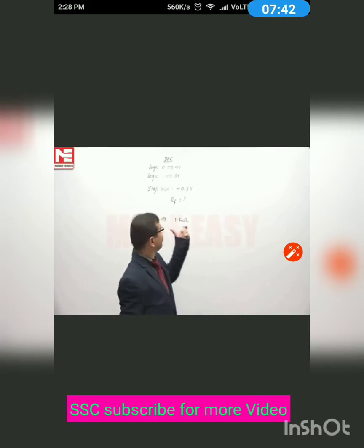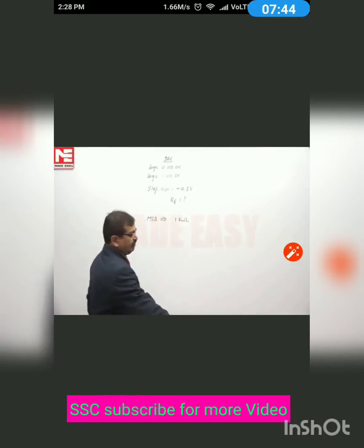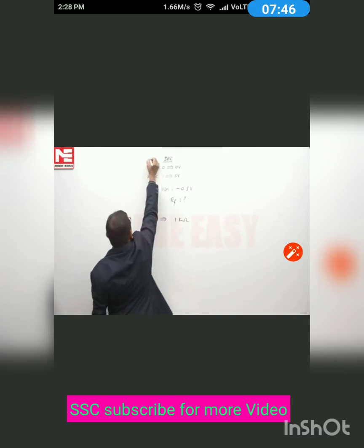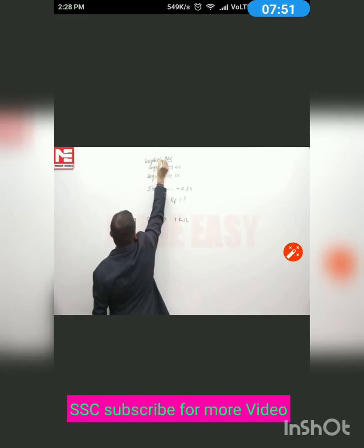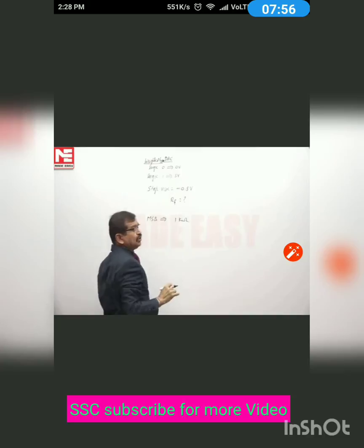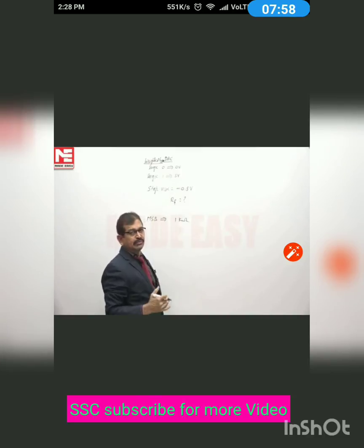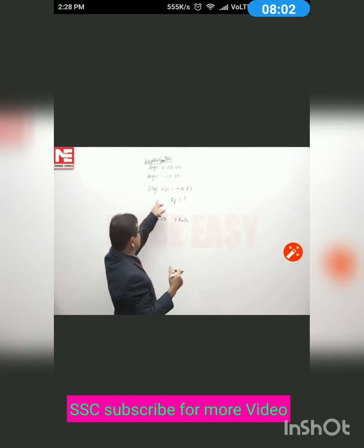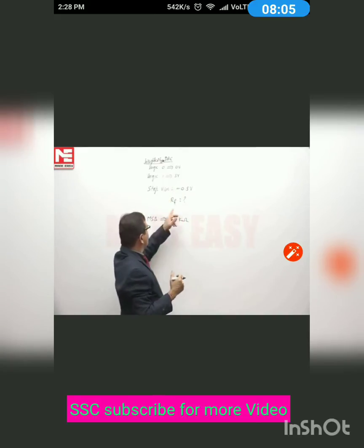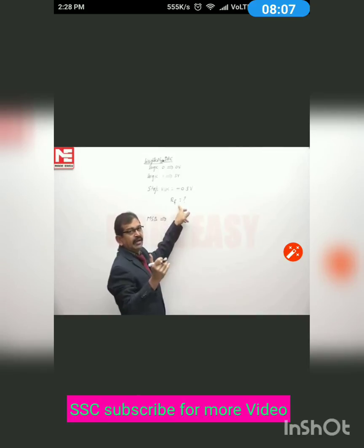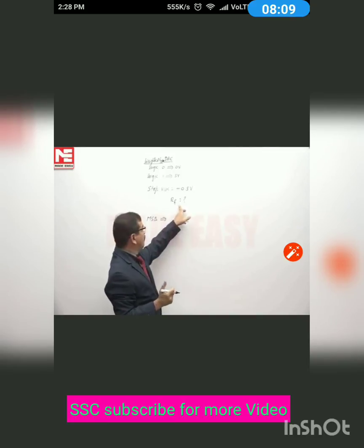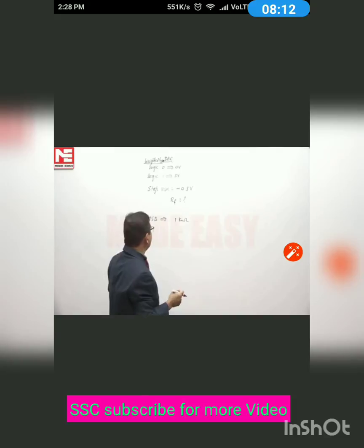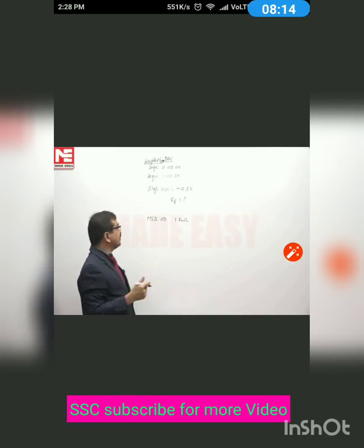We are looking here at a digital to analog converter of weighted type. The given circuit is a weighted type digital to analog converter, and logic 0 voltage is 0 volt, the voltage level corresponding to logic 1 is 5 volts, and we want the step size to be 0.5 volts. What is the RF, the resistor which is used in the feedback circuit of the op amp? What is the RF? That is the question.